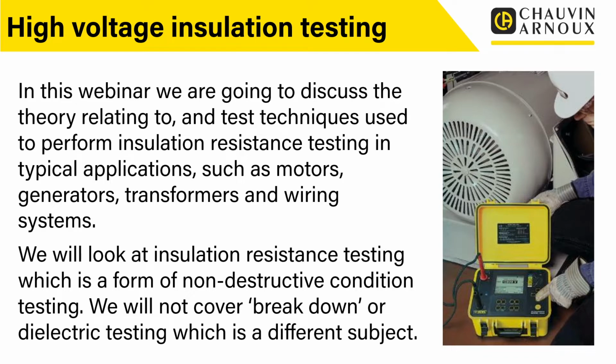Although we're using these applications as a context for our session today, insulation resistance testing is a very wide topic. We'll look at insulation resistance testing, which is a form of non-destructive condition testing. We will not cover breakdown or dielectric strength testing, which is a different subject. So very important, what we're talking about today is non-destructive condition testing. That term non-destructive is very, very important.